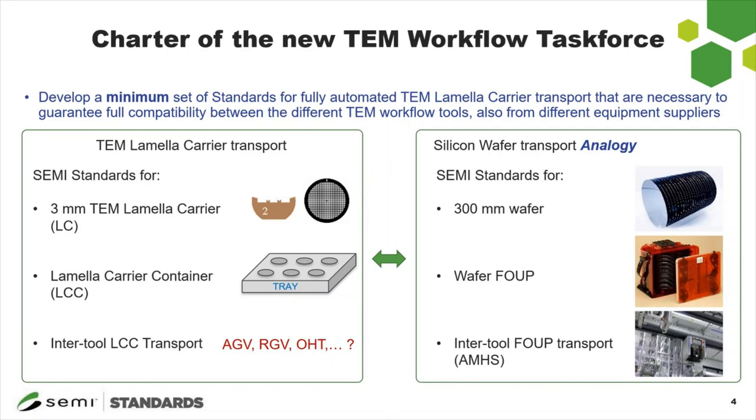When comparing TEM lamella carrier transport with silicon wafer transport, the two new standards would compare with the SEMI standards that exist already for 300 mm wafers and for a FOUP. And once these two new SEMI standards are available, one can work on equipment interfaces like EFEMs and load ports, and even on inter-tool transport definitions.